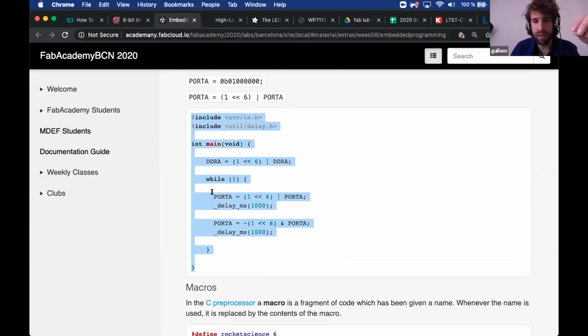So if you want our 3D printer to draw a circle and we need to synchronize 3 motors at the same time, and the time between when we give an instruction to the motor for the x-axis is delayed a few microseconds from the one in the y-axis, instead of a circle, we might get an ellipse. And so that's why it's important to keep things synchronized on time.